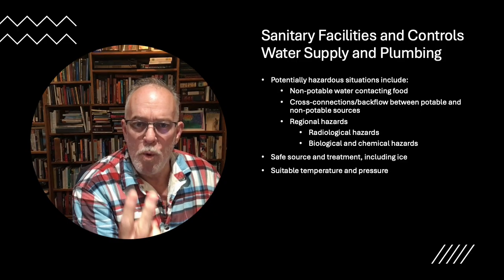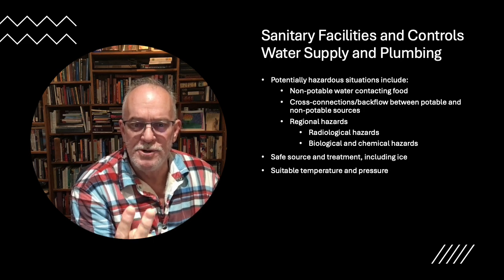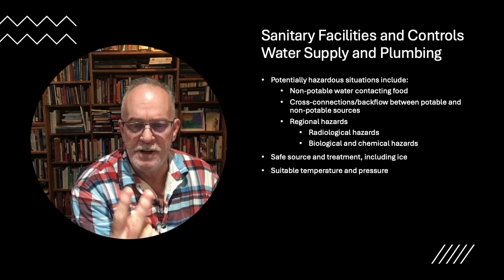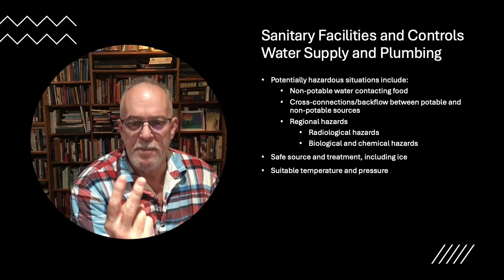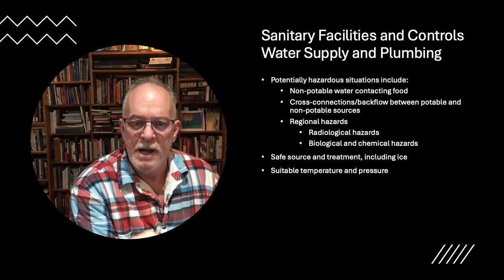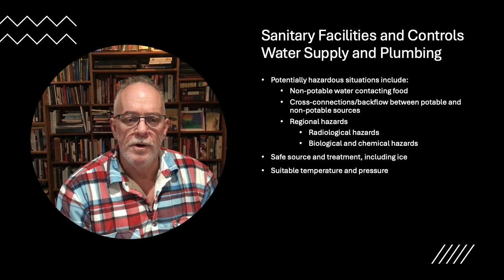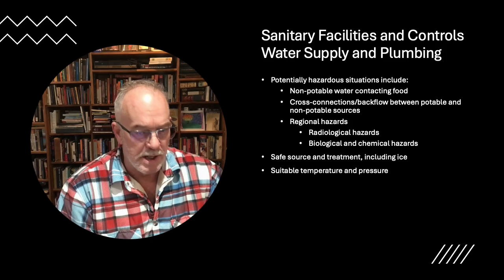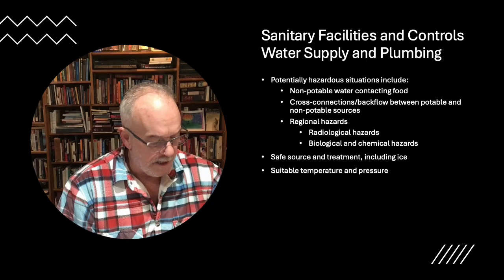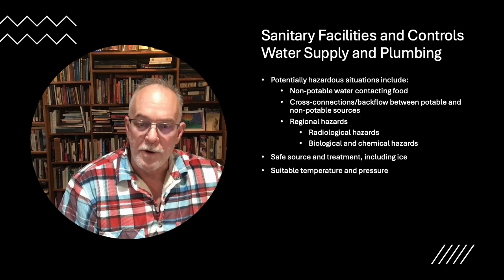How are you managing the water once you receive it? How's your plumbing? How's your fixtures? How's your potential for cross connection? How are you managing the water when you have it? And then what are you doing with the water? Are you using it as a food ingredient? Are you making ice with it? You want to make sure you know all the details to your water.